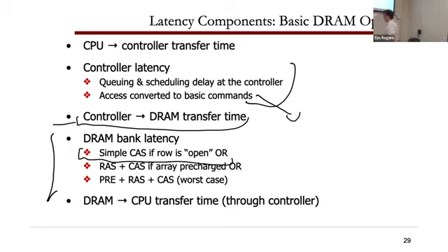So this is part of the reason why it's not just the caching system that makes memory accesses variable. It's also the memory system. If the row's open, it's quicker. If the row's closed, it's not. So if it was already open, then all you have to pay at the bank level is just the CAS to read that little chunk that you want.